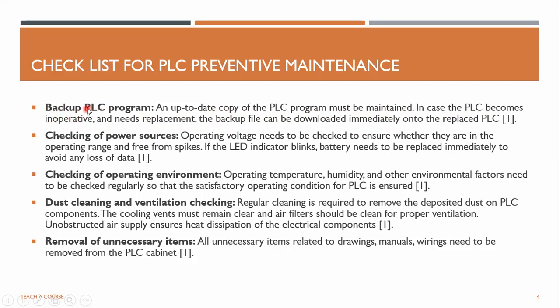So anyway, if you do some updates or anything, just back up your code, store it on a flash drive or somewhere on your computer. So if the PLC system goes down, you can just upload your previously stored program rather than spending hours re-implementing the whole system.